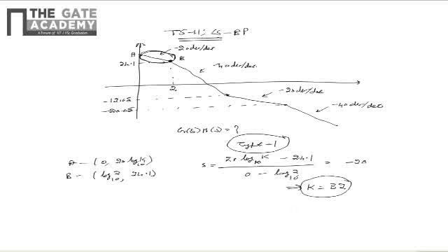Now let us analyze the line from B to C. The point C is marked as shown and let the corresponding frequency be omega 2. So similarly we can say that C corresponds to log omega 2 to the base 10 and the corresponding magnitude is minus 12.05.